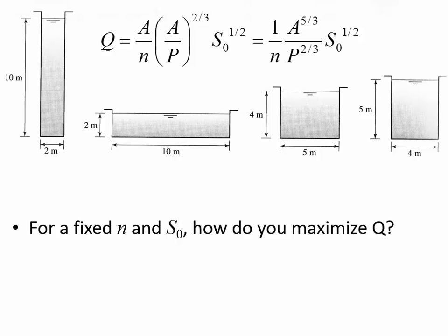The wetted perimeter is going to be radically different. Yeah. If we consider this as a wetted perimeter of 22 meters, because we've got 10 on each side and then 2. This, even though it looks like the same shape, it's a long rectangle, it actually has a wetted perimeter of only 14. Okay, here the wetted perimeter would be 8 plus 5, so 13.